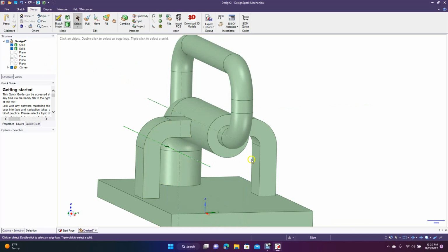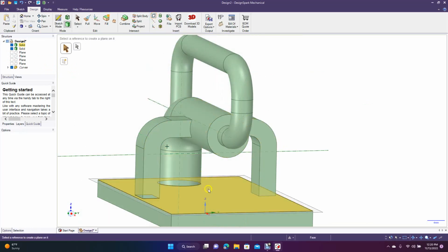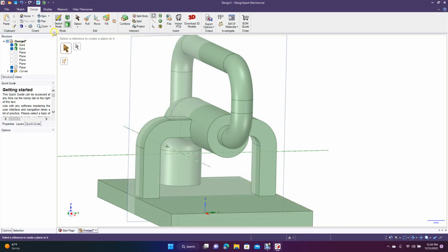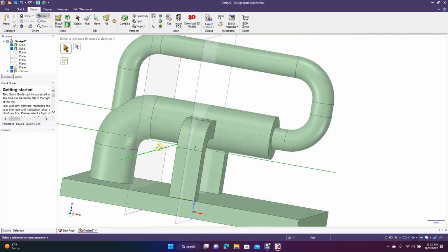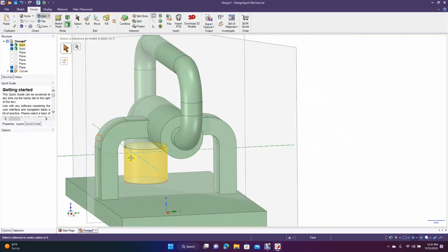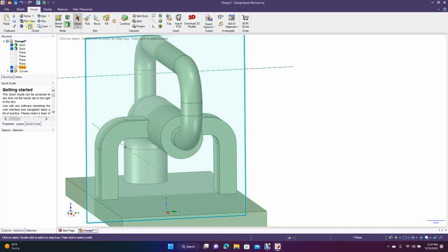So now we'd have to do one here. Basically you go back to your plane, and then you figure out where you want to insert that line. So we would have to do it here, on the red. Go ahead and click red, and then we'll spin. You notice it put it right in the middle of that plane there. So now we want to click this plane and go to plan view.